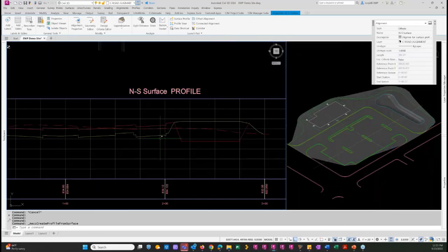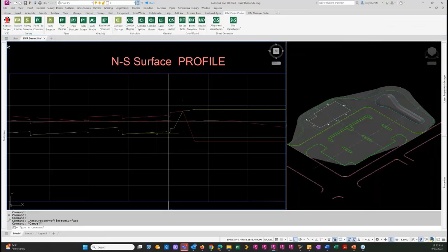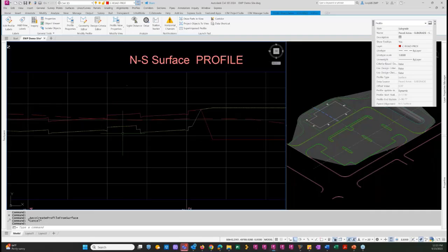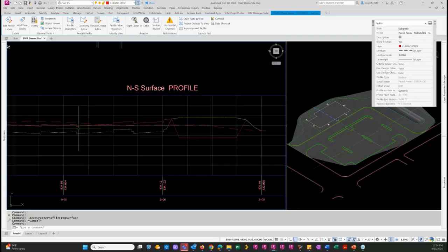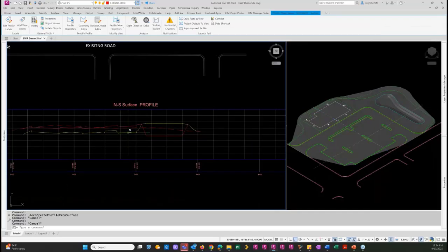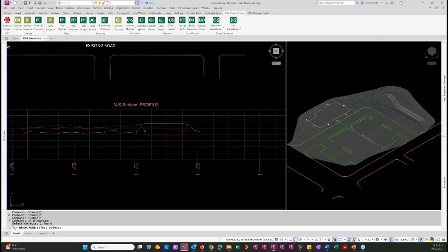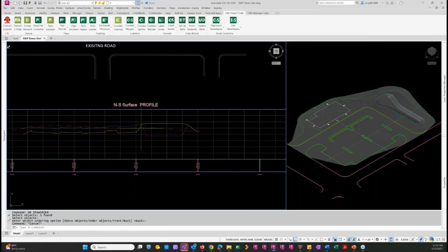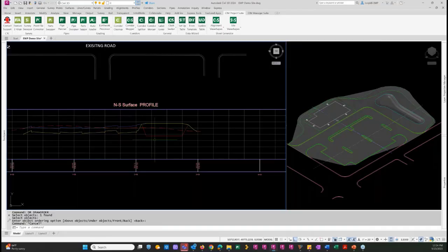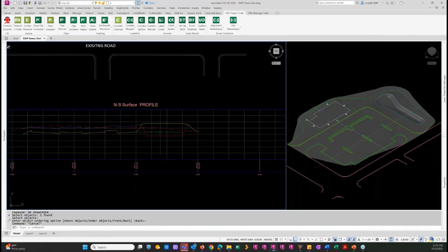So there's what we see right now. So here's my subgrade region. You can see it drops right down there. So I'm 2 feet here, but I'm 1.5 here. And I can change those at any time. Then here's my building. Let's change that draw order. So here's my building area. So all it affected, nothing comes out here. It's just the grading for the building. So only the volumes for that building right here.